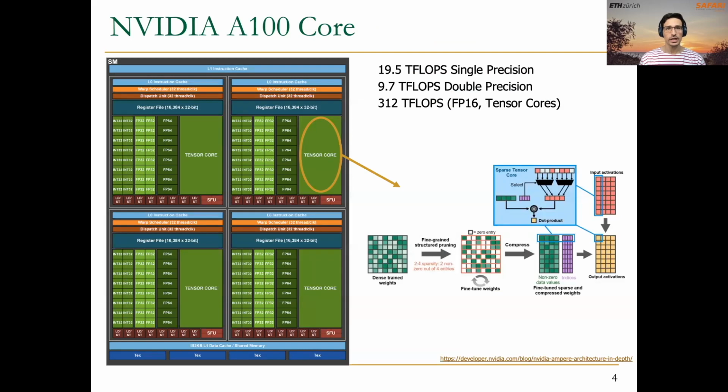And remember as well that inside the A100 core, the GPU core, we can identify different functional units that remind us what a SIMT processor is. It's not the only thing that GPUs share with SIMT processors in the way that we explained them in the previous lecture, because also GPUs use banked memories that we also introduced in the previous lecture. As an example of banked memory, in this A100 core, we have this shared memory.